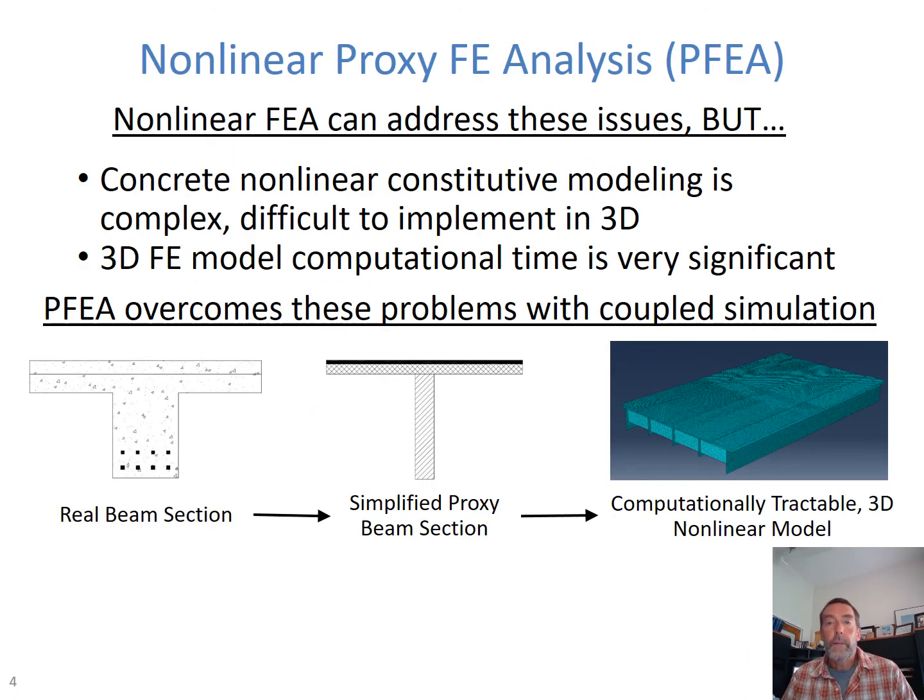Now, nonlinear proxy finite element analysis was developed to overcome those issues. We could go straight to a solid nonlinear finite element analysis, but concrete nonlinear constitutive modeling is complex and difficult to implement in 3 dimensions. The solid 3-dimensional finite element model computational time is very significant, and that's why we went down the road of proxy finite element analysis. It overcomes these issues with a coupled simulation, shown graphically in the bottom here.